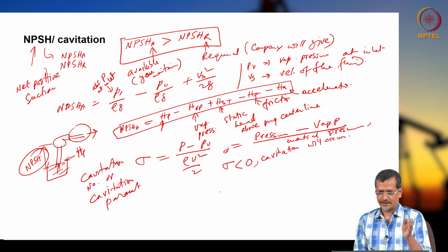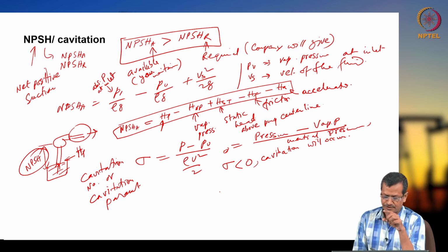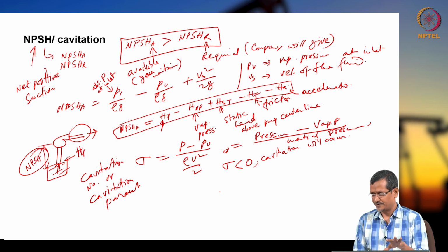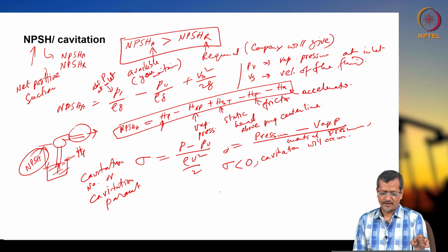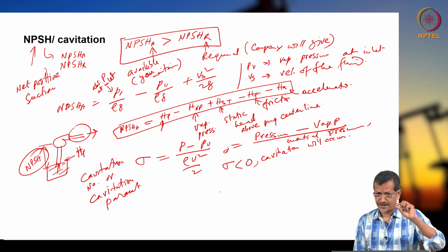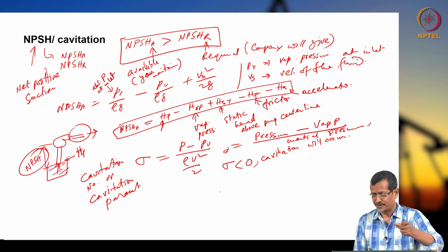You should remember NPSH is an important part when you are running a pump, and it relates to cavitation. The cavitation parameter also you should remember, and this basic formula, especially NPSH A and NPSH R and the full forms of those terms. Cavitation can occur at the impeller inlet where fluid is sucked, and then when pressure is developing, in that certain area cavitation will occur.